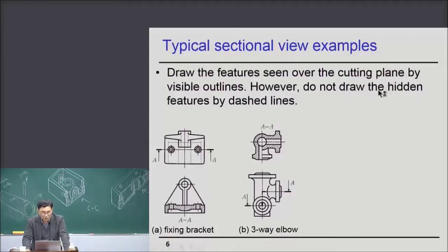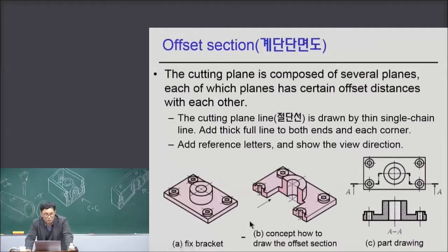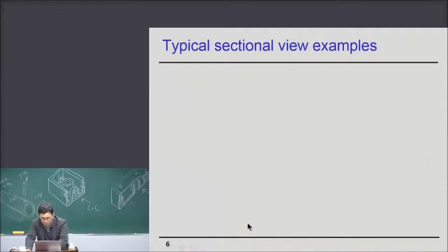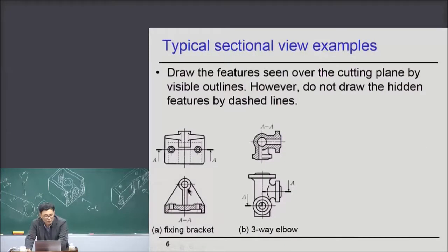However, do not draw the hidden features with dashed lines. The features which are seen over the cutting plane must be drawn on the sectional view here.